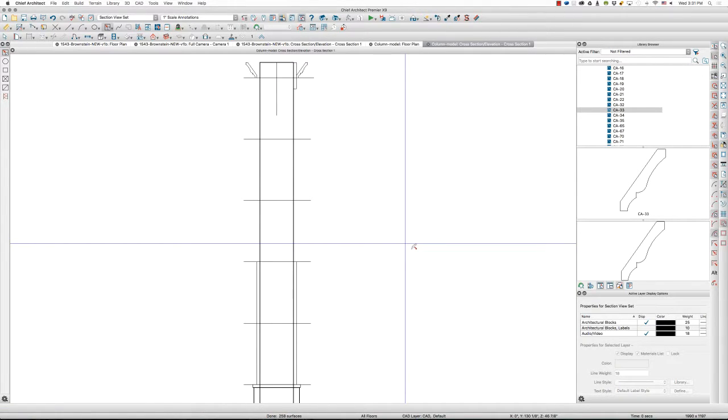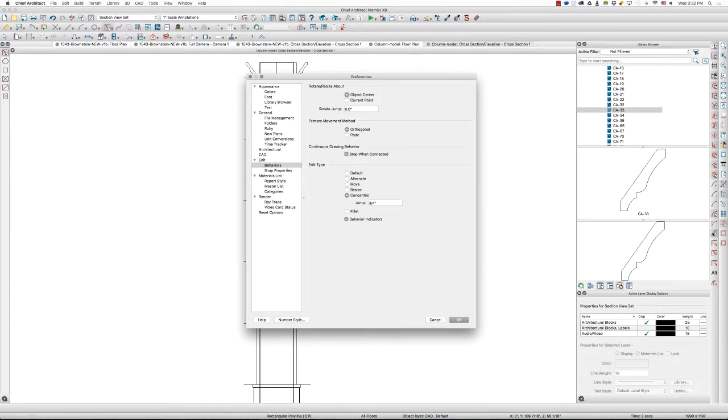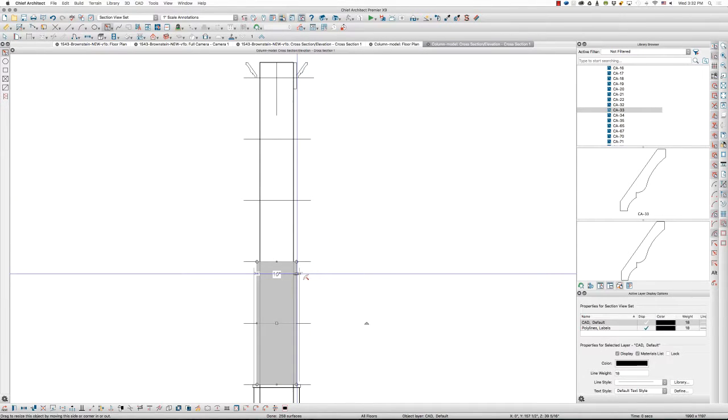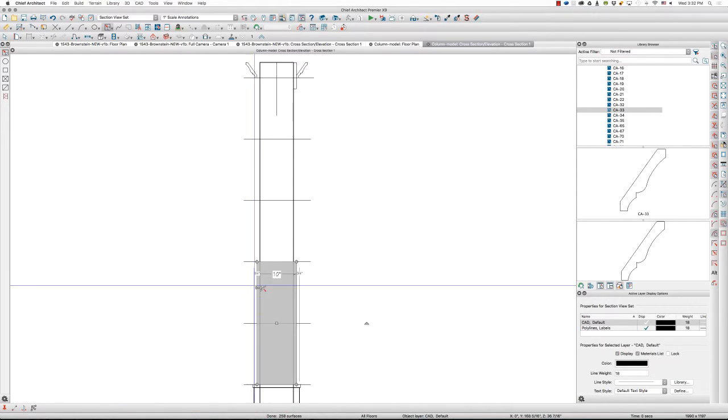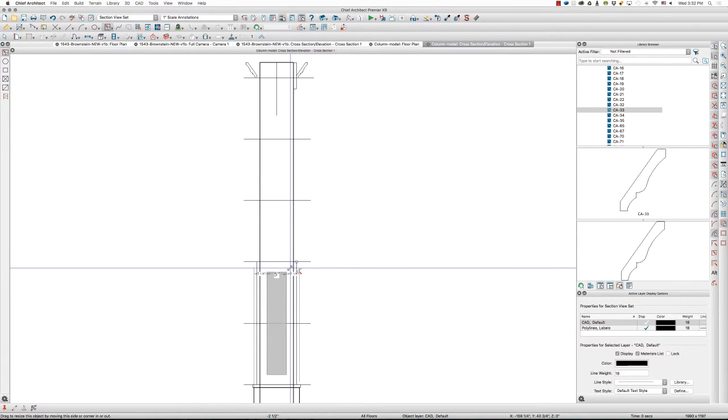Now, in here, I want this recess panel to be 2.5 inches. Top, bottom, sides. Okay, so I will take this 10-inch piece here and do a concentric jump. Double click on this, 2.5 inches. Select my polyline, copy, and drag this corner in like so.